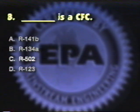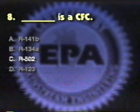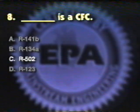The answer is C. R502. Be sure to know which refrigerants are CFCs. R141B and R123 are HCFCs, and R134A is an HFC.